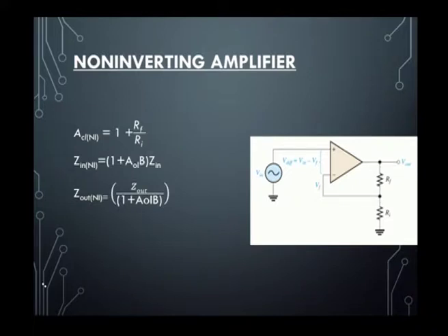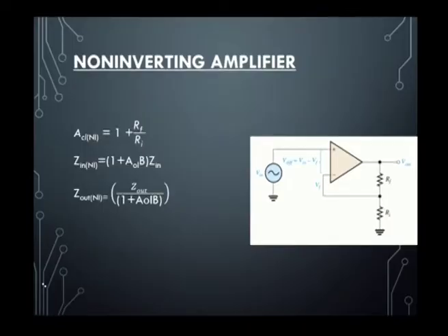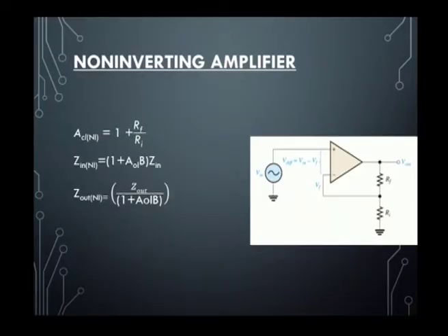As we already dealt with in the previous session, a non-inverting amplifier is an amplifier where the non-inverting or positive terminal of the op-amp is given the supply and the inverting terminal is grounded. For a closed loop, the inverting terminal has a negative feedback loop with feedback resistor RF and input resistor RI. The figure shows the non-inverting amplifier where we find Vin and Vdiff, the difference of input voltage and feedback voltage, with the negative feedback through RF and RI.